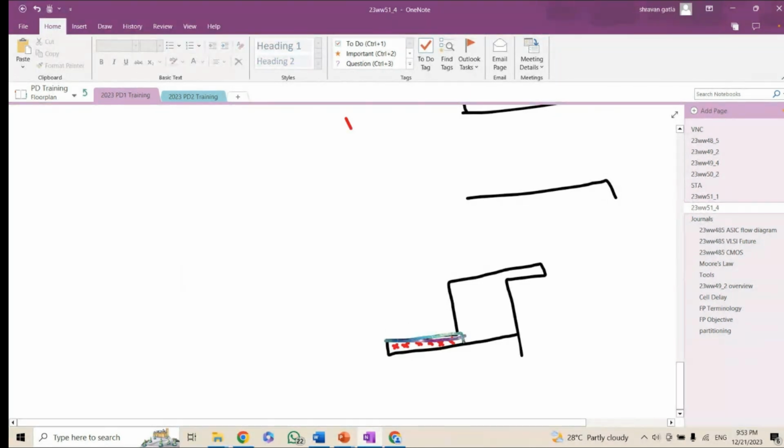This complete area is the hard placement blockage, which means no cells will be allowed to sit in this area. It is nothing but like you should feel like you don't have this area. But you can ask me, okay, why are they giving it like this?